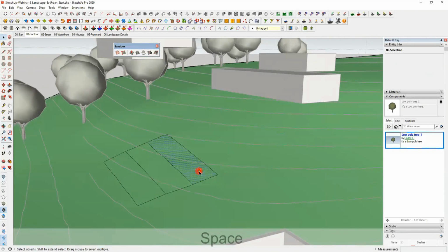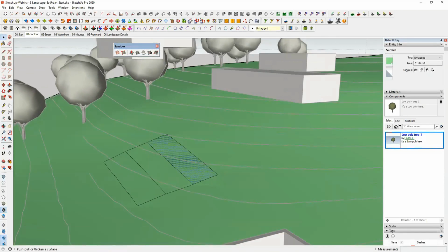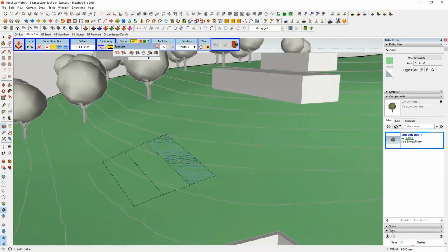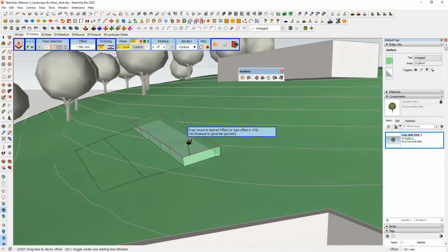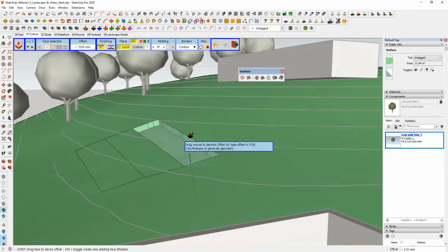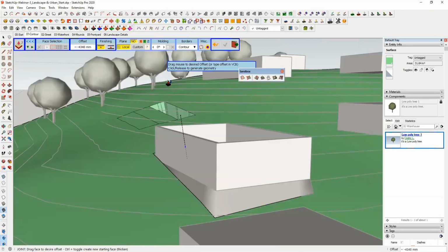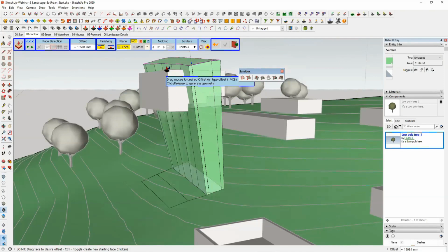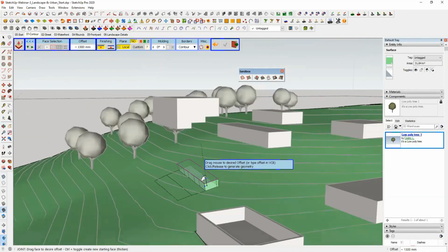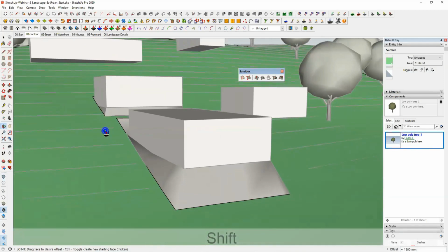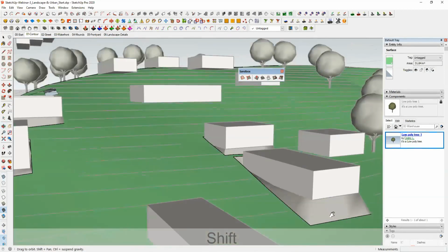So for that, we can select the face, go to join push pull, and make sure this time we pick this option and not this one, because we don't need the original face to be placed here. So we will select this. We can push it upward or downward. Now you can see that it is push pulling, and it is also changing in size, right? So we don't want this kind of effect. We want to have an effect we had in case of the stamp tool.